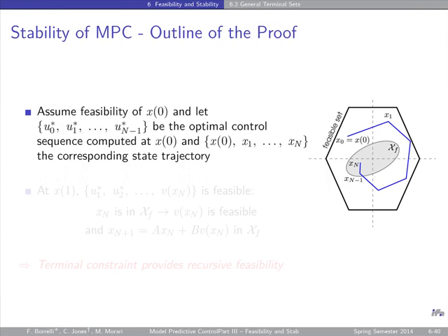feasible? Well, I don't know what MPC is going to choose as an optimal policy, as an optimal input, but I know that there exists one, because I can take the shifted sequence, u1, u2, up to un minus 1, okay? And at the end, instead of 0, remember 0 had the role of, if you are in 0, you apply 0 and you stay in 0. In the end, instead of 0, you apply this Vn, which by assumption exists. There exists a Vn that keeps you in XF. Okay?